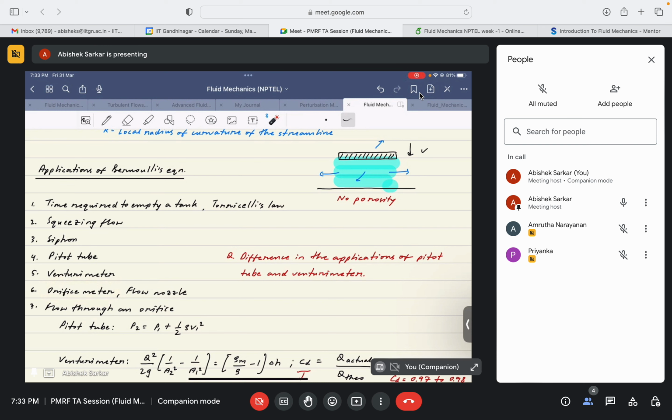But again, depending on the use, we can consider some inaccurate measurements, say in some factories. If there can be some plus or minus tolerance values, and we can have some inaccuracy in our measurement, then we can use an orifice meter there. Accuracy is not the fundamental need in that case; we want to have lots of pipes and lots of systems where we need to measure the flow field. That's why we use an orifice meter instead of a venturimeter, right?